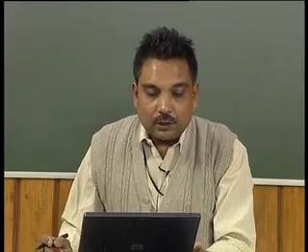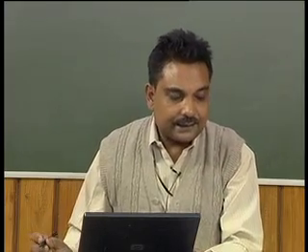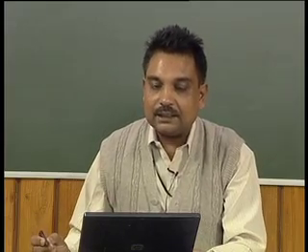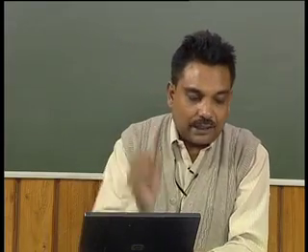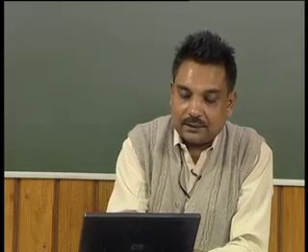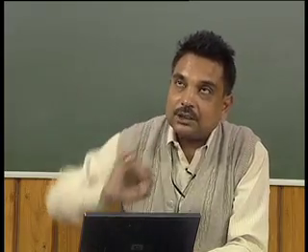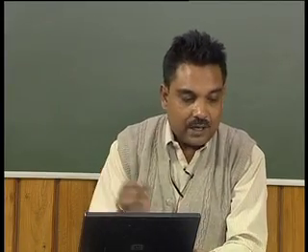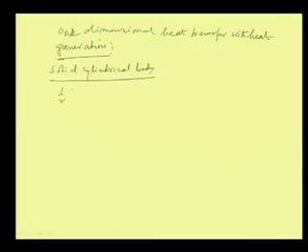Now, when there is a solid cylindrical body and there is heat generation, because it is one dimensional heat transfer, I will not write all the things. What I will write is the simple form, I think by this now we have understood how to reduce the general conduction equation into simplified form. So, what I will write is 1 by r d dr. Now, I am not writing a partial differential form, because we have taken it to be one dimensional, and also we have decided in this particular discussion that it is steady state heat transfer.